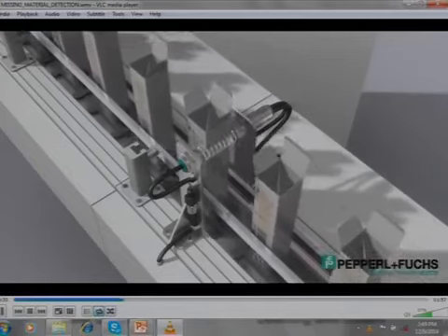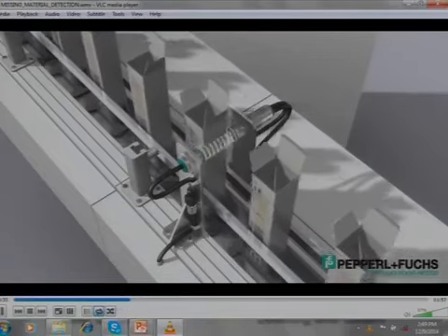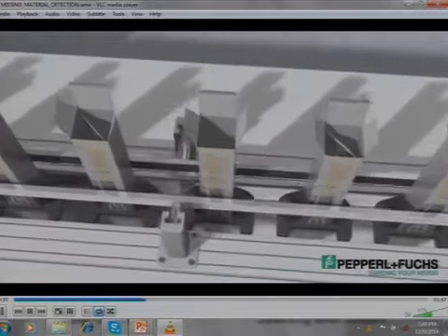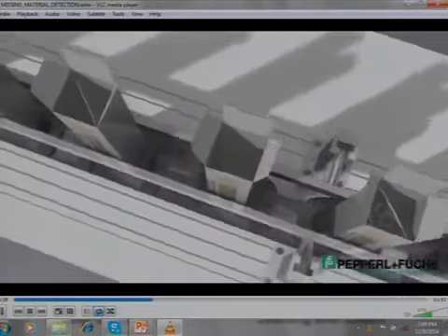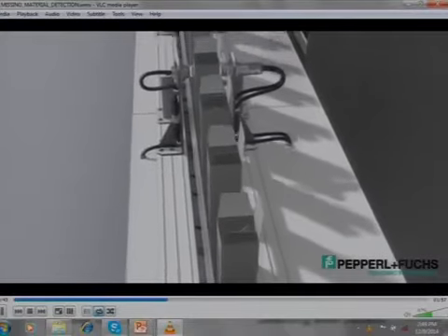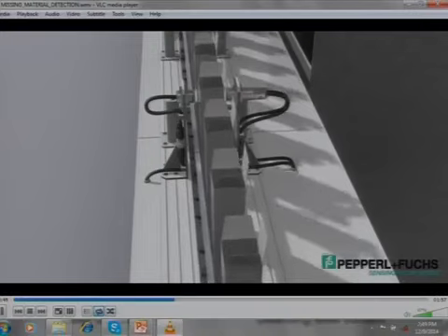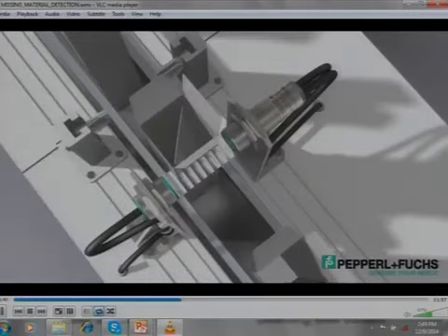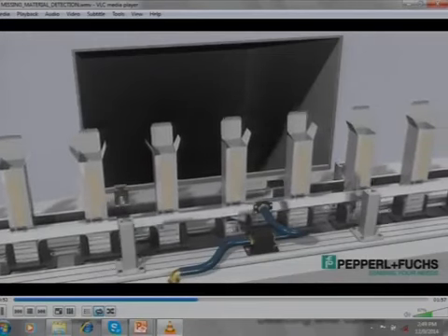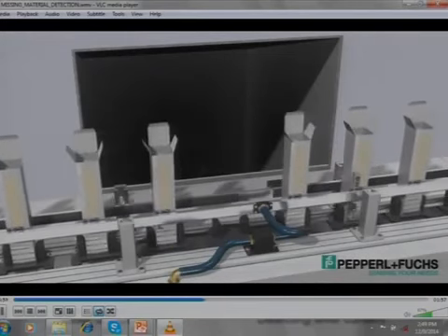Now, because of the target inside the pouch, the amplitude of the sound waves being received by the receiver gets reduced as compared to an empty pouch. So the amplitude is being measured, and based on that we can get an output. When the pouch is empty, it can give an output, it can stop. That is the control part. You can get an output from the sensor.